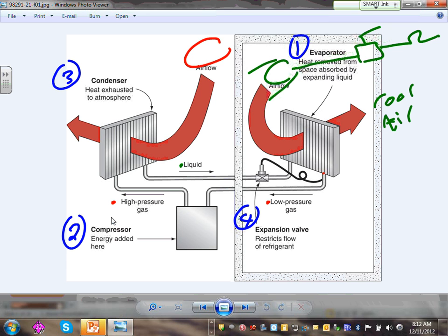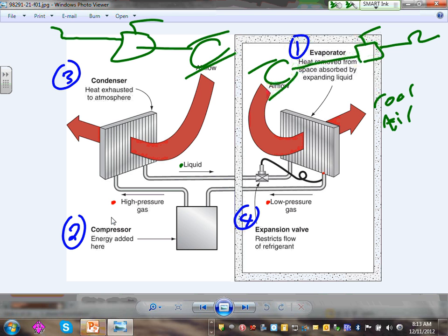My electrician will come over here and put a disconnect and overcurrent protection device, right? Here's another blower outside, blowing air right through this condenser to remove the heat from the liquid. So this is hot air. Does everybody see how the hot air comes from here, collects through the refrigerant, and gets out to Mother Earth? Does that make sense?